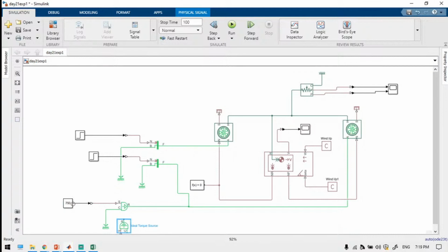By default, if you are applying a motor, we cannot feed the torque value directly. We know the voltage of the motor, and if we change the voltage, then we can adjust the speed of the motor. Indirectly, if you know the motor power, then we can calculate how much torque can be delivered by the motor. So now we can estimate how much torque we need to rotate at the same speed.